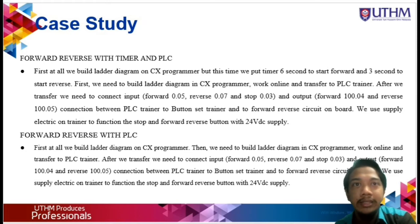We use the same addresses as our forward reverse with timer: forward 0.05, reverse 0.07, and stop 0.03. The forward output is 104 and the reverse output is 105.